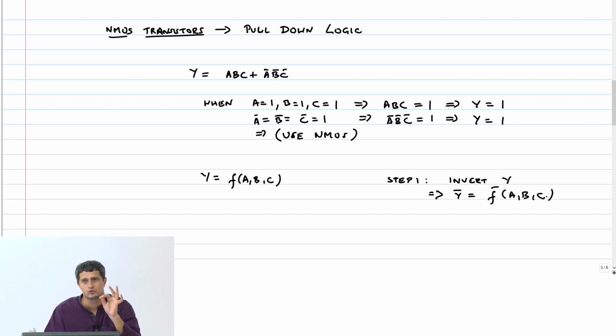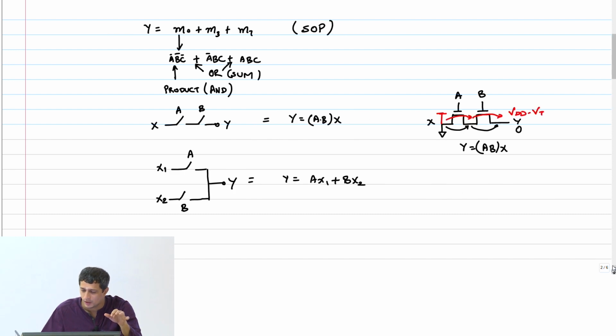We will look at what we should do for the PMOS in some time. Because I want to get the output to go to logic 0 with the NMOS, but only if I invert will the actual logic be correct. And that's why static CMOS logic is inverting by nature. So you can use this idea that if you put two NMOS transistors in series, or n NMOS transistors in series, you get an AND condition. If you have an OR condition, then you just put them in parallel.